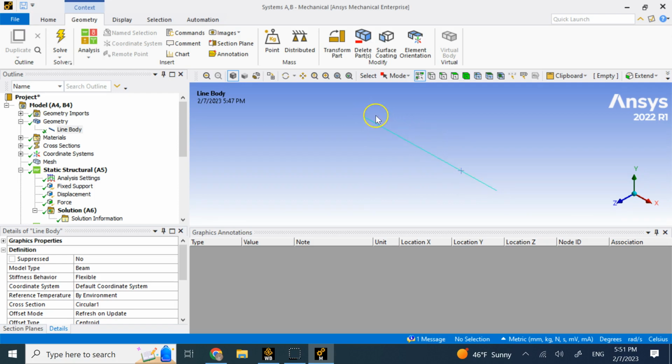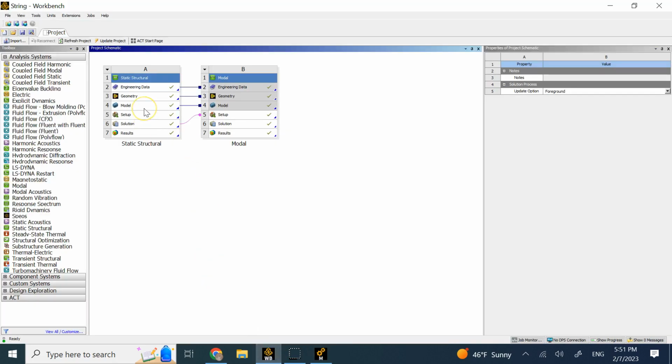Before you let it go, that initial shape is a static deformation, because you applied some force, let's say in the middle, or applied some displacement, and based on that the total shape of this string would change. If I move the middle point, the rest of the string would also change shape. It's not going to stay straight, it's going to go up a little bit and then go down. So if I want to get that initial shape when I just moved one of the nodes up, that initial shape comes from static deformations. So to provide that, I need this one as well.